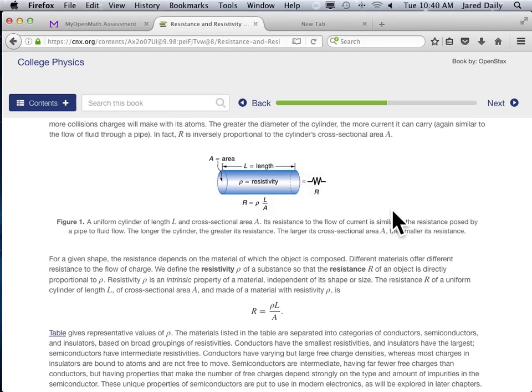The area should be 0.0005 squared times pi, or 0.001 divided by 2 squared times pi. That's right. That's the magnitude. So it should be something like, maybe it starts with an 8. What's your number? 7.85e-7. Sounds right.